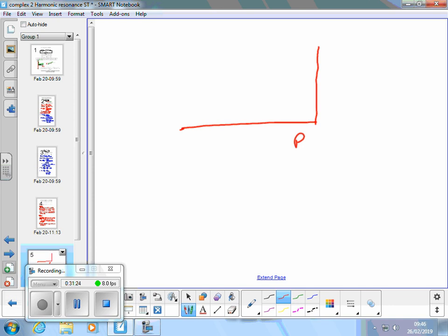We've got inductive power, which is called Q, and then the apparent power, S. The cosine of this angle is called the power factor. The more inductive load you've got, the longer the S line gets, and the current increases for no more power.